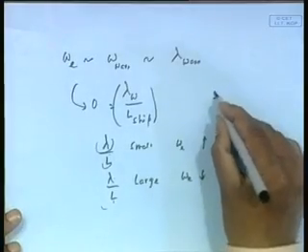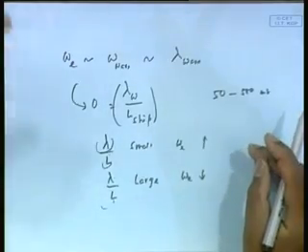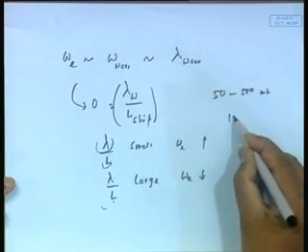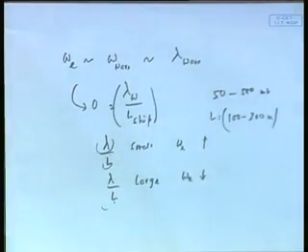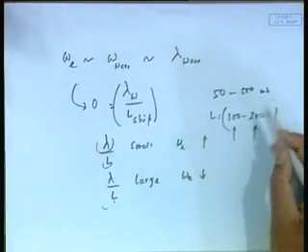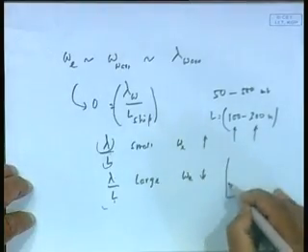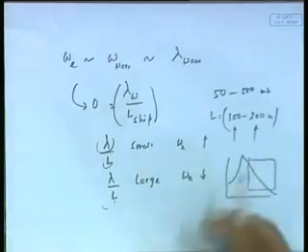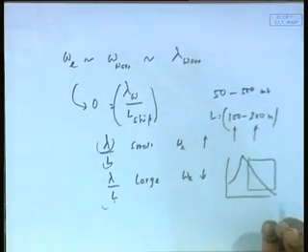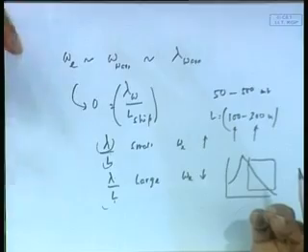Now, going by the open ocean, 50 to 100 meter waves, 500 meter wavelength, obviously what happens is that a 50 meter ship feels a 500 meter wave as 10 times its length. But a typical ocean going ship is something like 100 meters, 200 meters, 300 meters. A VLCC may be of this range, and a typical small cargo ship also of this length. So for a 300 meter long ship, there are waves which are 200 meters, that is going to be small, and therefore for practical large ocean going ships we are in this region. You see, I cannot avoid studying hydrodynamics. I am trying to emphasize that large ocean going ships would encounter waves where the encounter frequency is moderately high and therefore inertia force dominates.